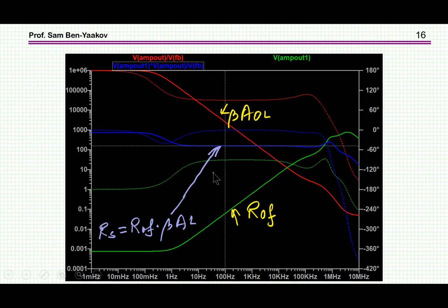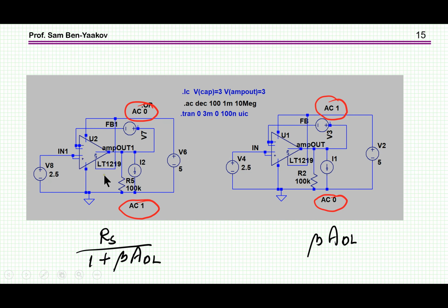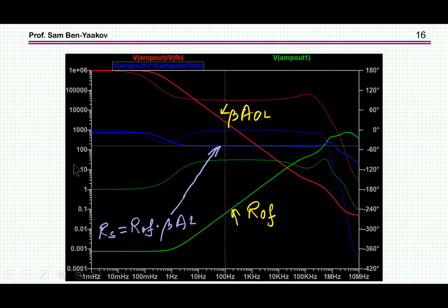By the way, as I've noted in the earlier video, which I've linked here, although I'm using here the same amplifier as I've used in the PSpice, the performance of the model is a little bit different. So the models are not exactly the same between PSpice and LTSpice. And therefore the value of the output resistance is also not exactly the same.